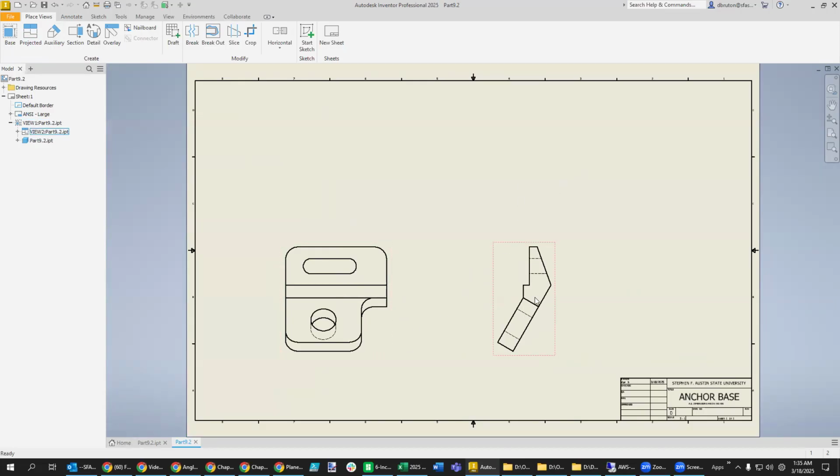I'm also seeing that the face we want to use to make a circle is this one. So this one's already facing us, but that one's not facing us. And so if we showed a top view, if I show you what that one is, you're going to find out that that's not really going to be what we're looking for. You see that in this case right here, if I create that, neither one of those are circles or arcs that are the plane of which is facing you. So that's why we don't really want that view. We want to have a projected view instead.